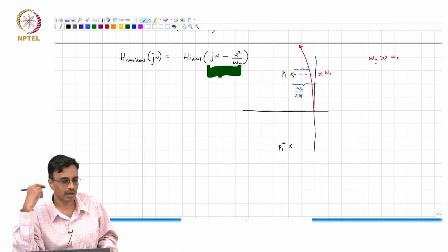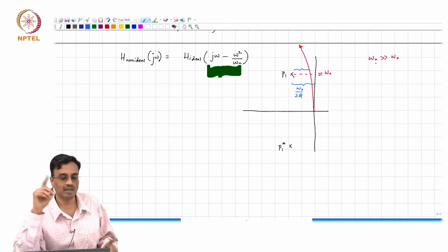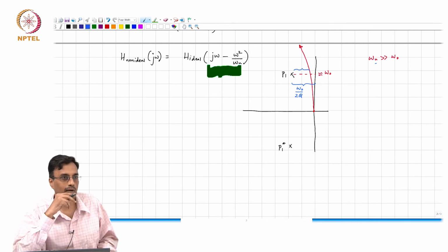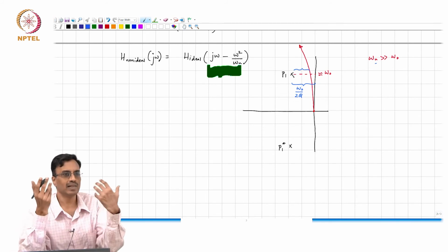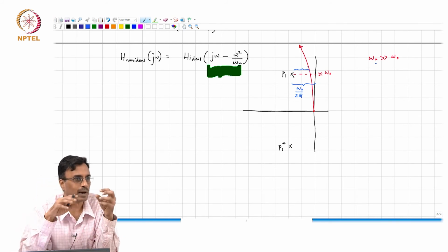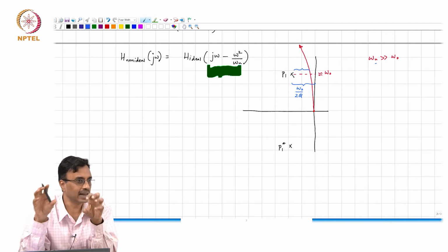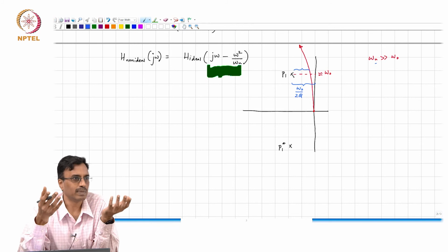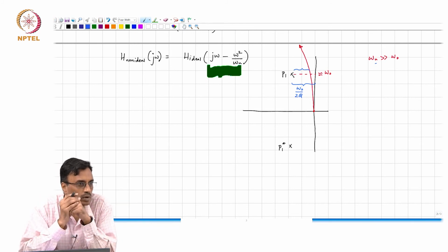It is smaller, right. So, therefore, do you think the filter is, within quotes, more stable or less stable now? Less stable, and intuitively that makes sense, right. We have a negative feedback loop. In that loop now there is extra delay because of finite bandwidth of the op amps, and as a result the feedback loop is tending to instability.